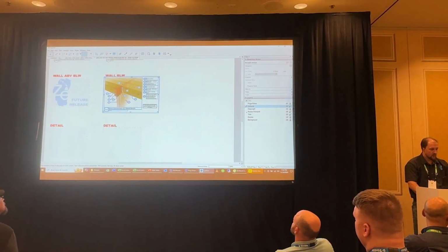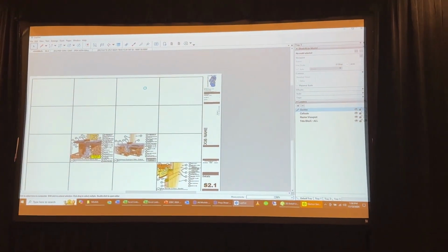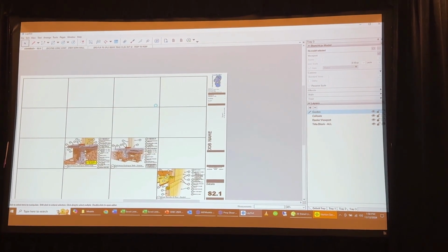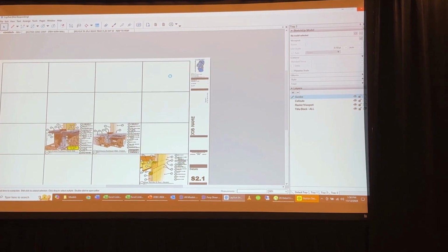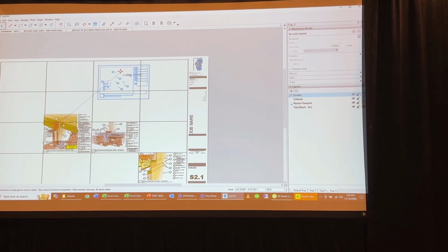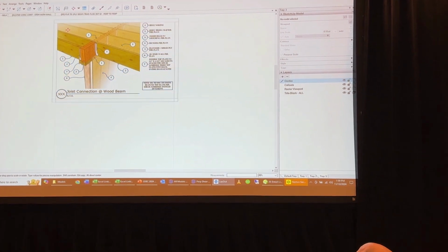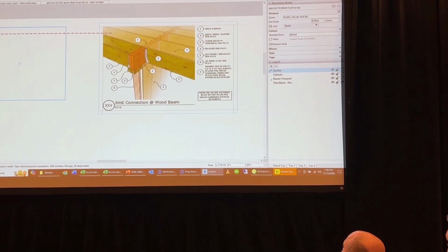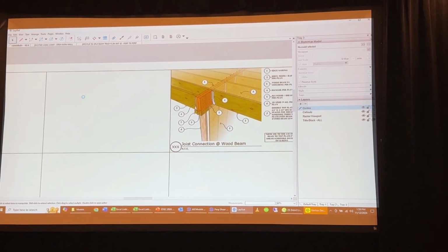That's where you do keynotes. And this just goes back to the scrapbook thing we talked about really briefly. Let's just say we didn't have this one labeled already. I'll just grab the scene. The old school way, and probably still done today, was that all keynotes would be done CSI style. You're always looking at a 5-digit number.